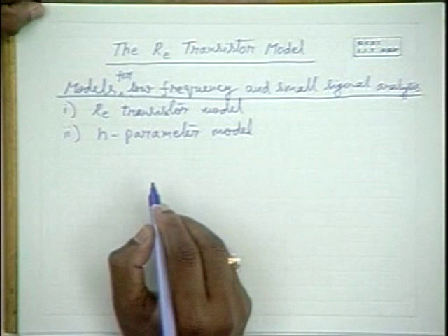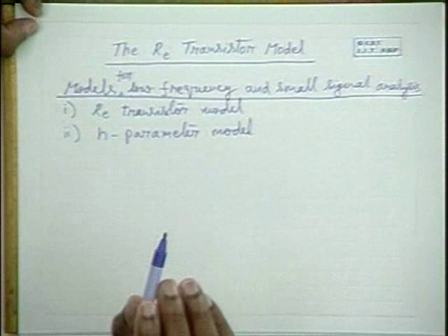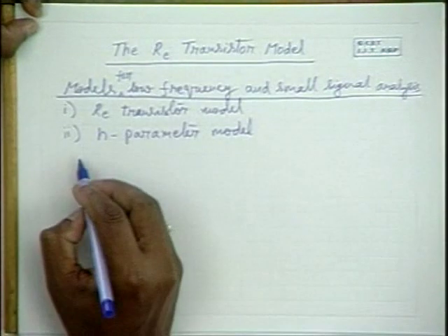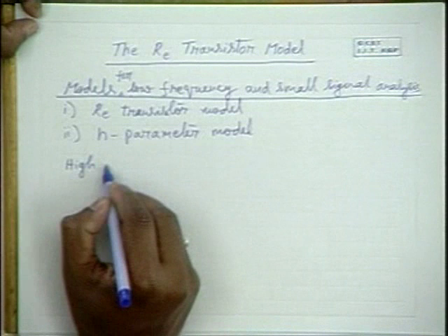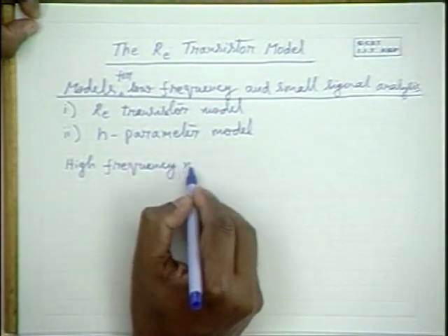Now for high frequency analysis, say you are interested in the RF amplifier in a communication receiver, it is a high frequency application. You have the input frequency running into several megahertz. Depending on the application, it ranges from megahertz to millimetric waves. So in such circuit analysis, we use the high frequency models, again small signal models.